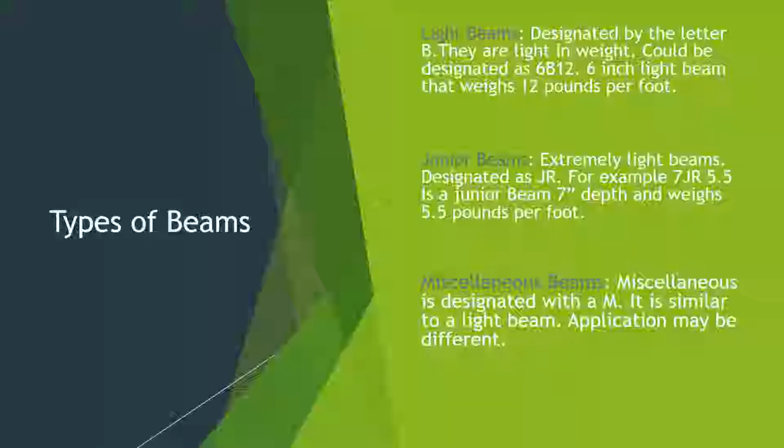Some of these lighter beams will be in the interior of our building. These are mostly used as intermediate steel, filling in areas where more load bearing is required. Where heavier beams can't fit, we'll put these smaller beams in. And you'll see them in the framing above windows and door openings. So they're great little beams for the interior of the building.